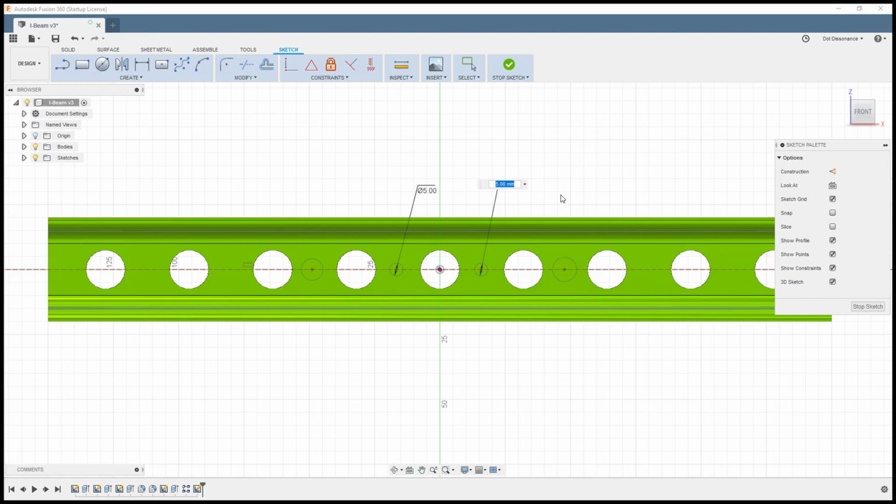So a common theme in all CAD programs is to associate this one here with maybe one master. And just to be a little bit more particular, I usually make this one be the one that's over on one side, like say the main one at the top over on the left. This is the one that you edit and then it cascades down and changes all the rest. So I want this one here to be the same as that one, okay? And so now when I hit enter, it will be the same. And if I change the first, it will change with it. But what I want to point out before we go on is this right here. The D27, we're going to see something like this in just a second when we get into the edit parameters section.